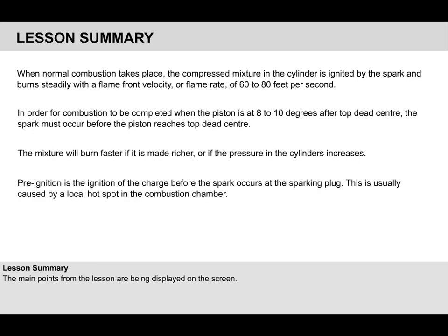Pre-ignition is the ignition of the charge before the spark occurs at the sparking plug. This is usually caused by a local hotspot in the combustion chamber. When you are happy with these points, move on to see a summary of the causes of and the methods used to prevent detonation.